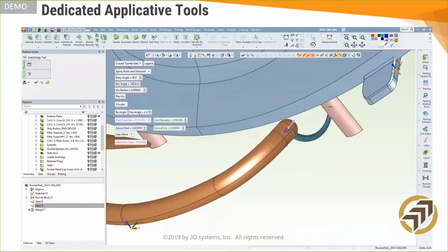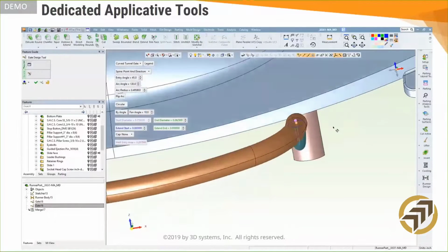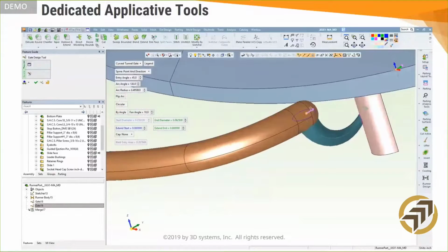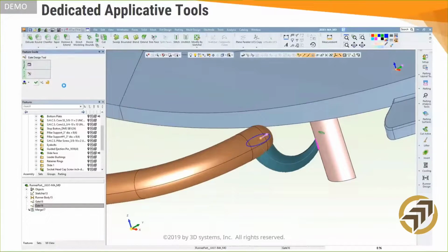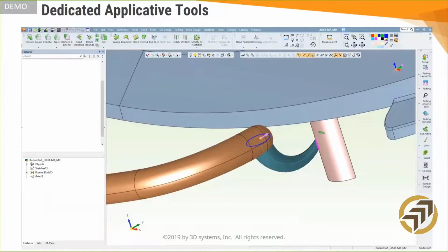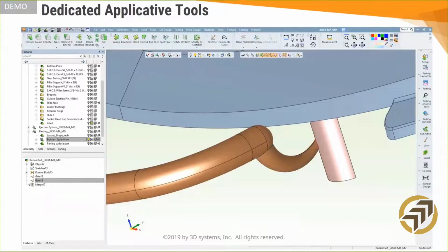As you modify the gate and consider the preview on screen, feedback about the area of melt entry to the part is provided. The design assembly understands the general structure of a mold, but none of these steps have to be done in any certain order. This allows for a very open flow of design, where known information can be added now, but unknowns can be added later.